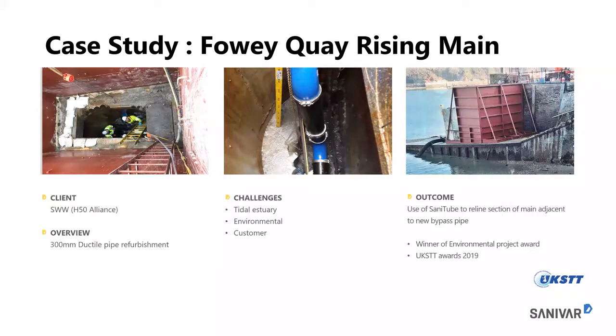So effectively, the outcome was to use Sanitube to reline the section of the main adjacent to a new bypass pipe. We used a coffer dam, which you can see there on the right hand side, to extend the working time in the well, and we inserted Sanitube out into the estuary to refurbish the old 300mm pipe, and that was a successful submission for the environmental award at the UK STT Awards in 2019, which seems like an age ago now, but there we are. Very successful project.